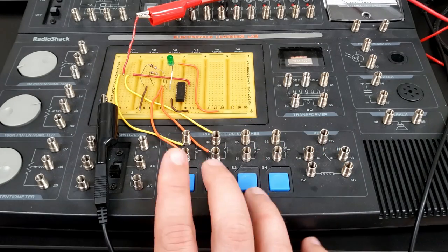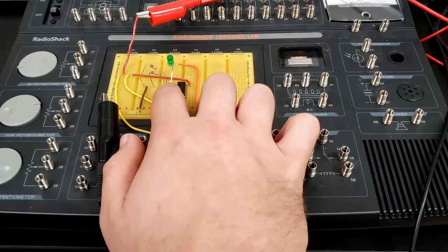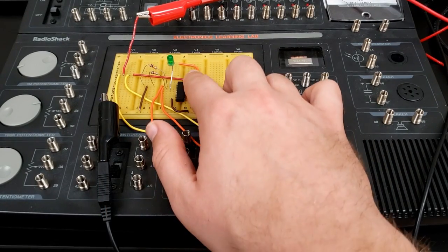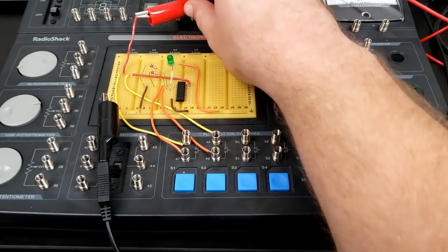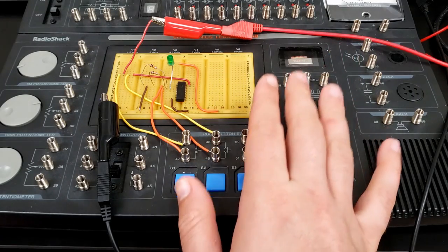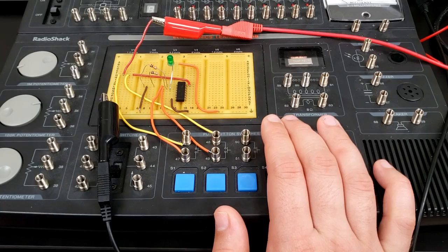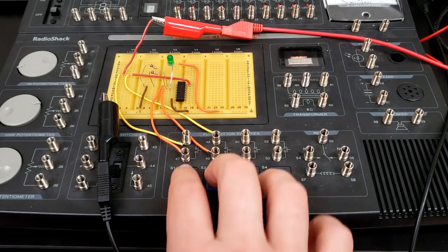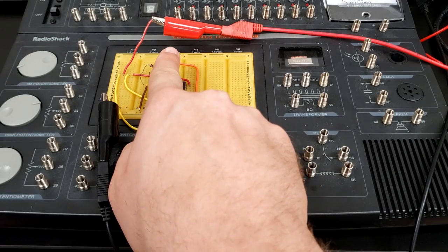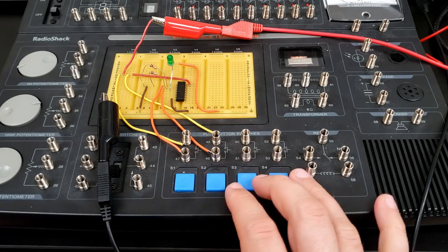We can see that we have our 2 switches here, and each of these 2 switches runs to two of the input pins on our integrated circuit. Then we also have our grounding pin grounded and our VDD pin being supplied by our power, which is running to our variable DC power supply, which I will just not show. You'll just take my word for it that it's over there supplying power. Then we'll press these switches, which will change the input going into here, and then we'll get a different output, and our output is running to this LED. So the output pin of our integrated circuit is running to our LED right there.